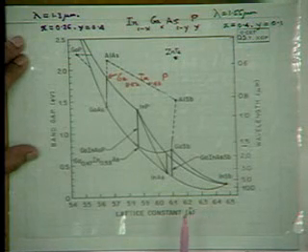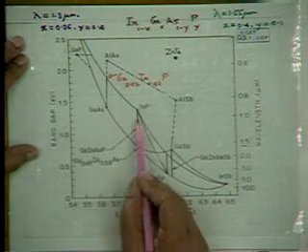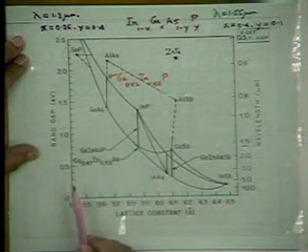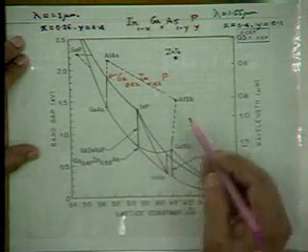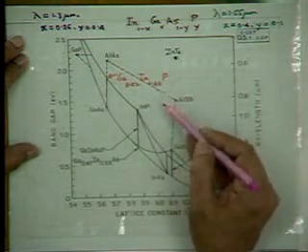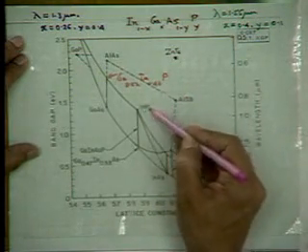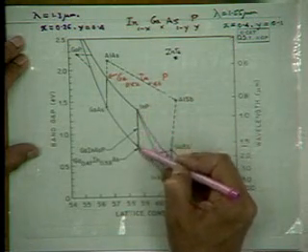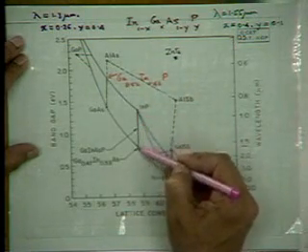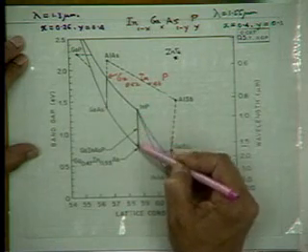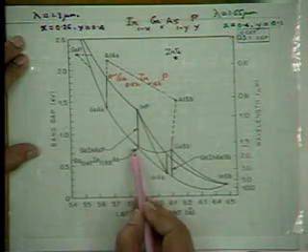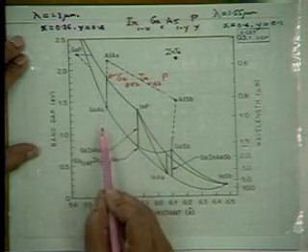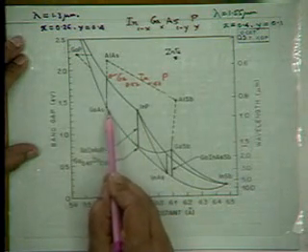So we find that for fiber optic communication we have to use materials based on indium phosphide as a substrate, and if we look at this vertical line, this corresponds to materials having this quaternary composition gallium indium arsenide.